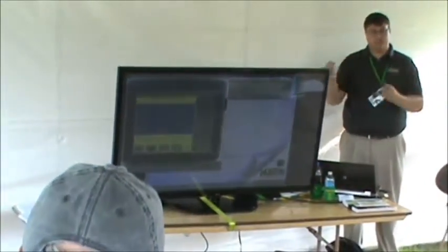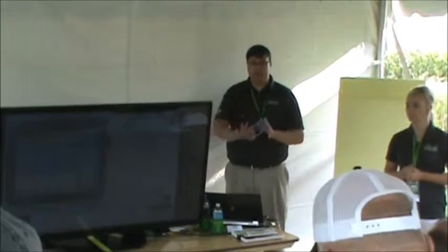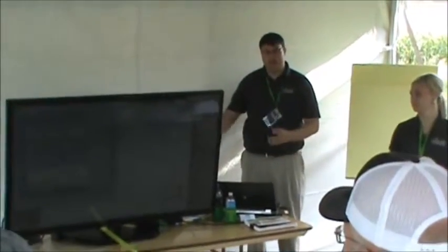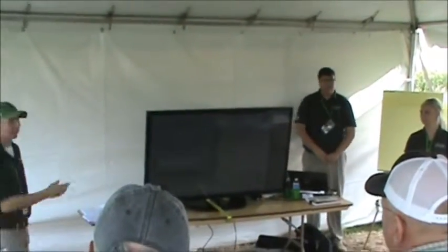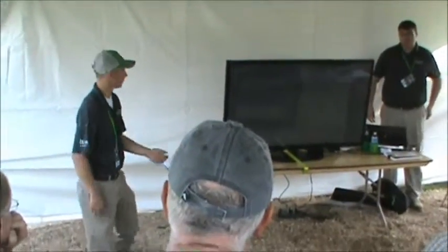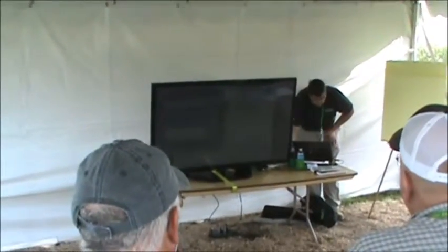Another thing on Layout Manager is if you're setting this up and you get a message that says controller not found or something like that, it's because you've taken your display straight out of the planter or the sprayer and put it in your combine, and it's trying to find that sprayer or that planter for that given option. We just need you to go back in and reselect it because it's trying to find a controller that's not there, because you're not pulling a planter with your combine. It's not the same controllers, so you need to go in and reset it. So essentially, the display still thinks you're talking to the sprayer or the planter, when in all reality you're talking to the corn head or the bean head. Is that it, Susan? Yep.